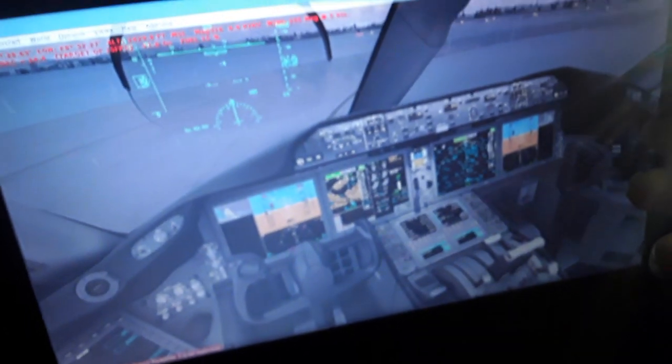So you will see also we use 15 degrees of flaps for takeoff. We're gonna select the runway. We have the Zurich International Airport and runway 14 for takeoff and for landing. So we're gonna select this airport and this runway. The flight management computer is gonna calculate the runway length, the runway slope, the wind direction and speed, the barometric pressure, the density of the air, and the temperature, and also the runway conditions. It will give us the takeoff speeds V1, V rotate, and V2.